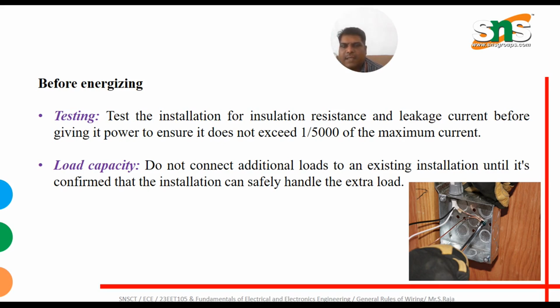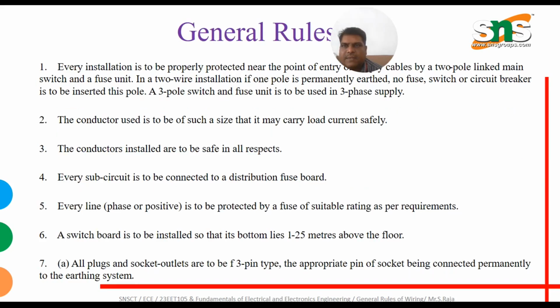Load capacity: don't connect additional loads to an existing installation until it's confirmed that the installation can safely handle the extra load. This is the general rule which is given. Every installation is to be properly protected near the point of entry of supply cables by a 2-pole linked main switch and a fuse unit.